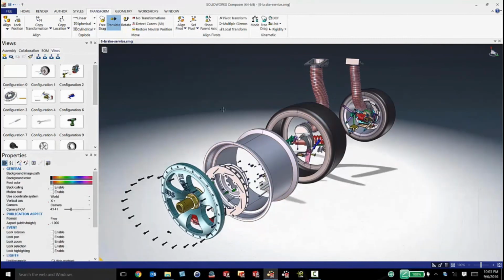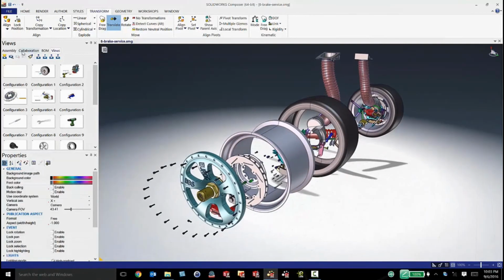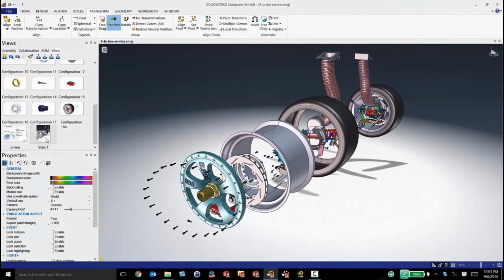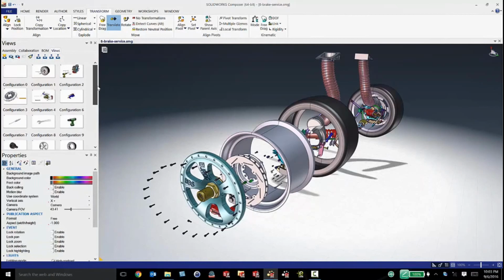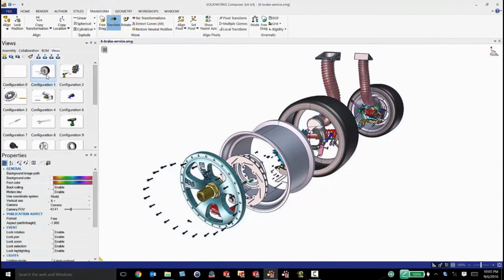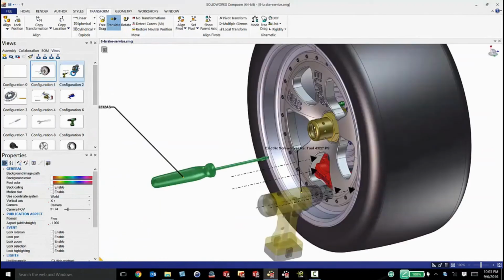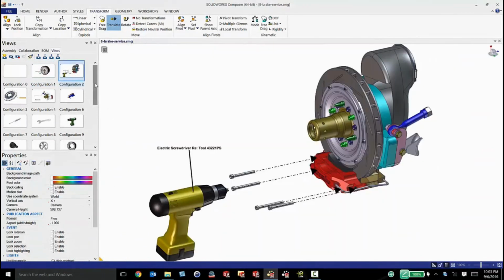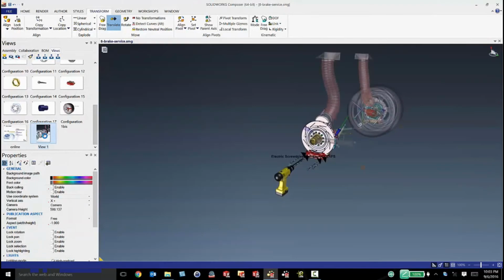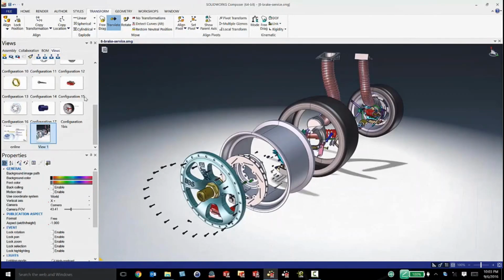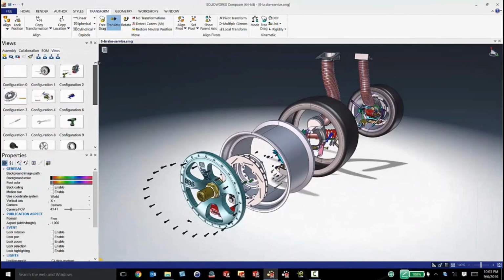So all of the parts, once you get them into Composer from the CAD file, are considered actors. So we've got part actors, and then we've also got something called collaborative actors. So I'm saving a view here, and I can switch to one of the views that was already saved, and then I can, of course, take a look at any of these pre-saved views in here, and then anytime I can go back to my view. So the views, if you're just worried about 2D content, the views are what you're really trying to work on.